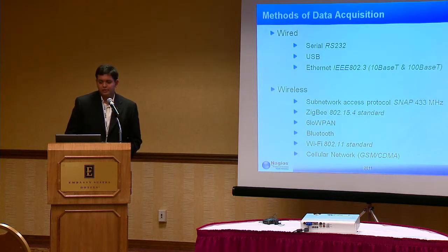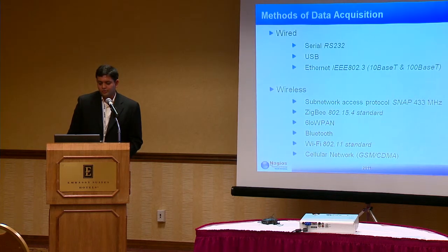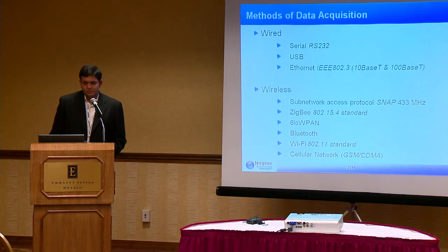We use the 802.11b in most of our products because, although you may wonder why we still stick to B when G and N are there, the reason is B takes less power. So if you want a battery-operated application, it does a better job if you use B.